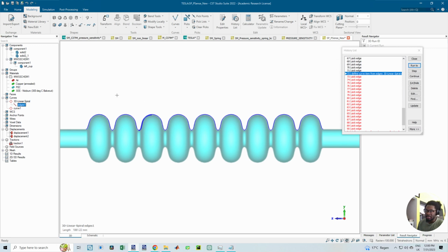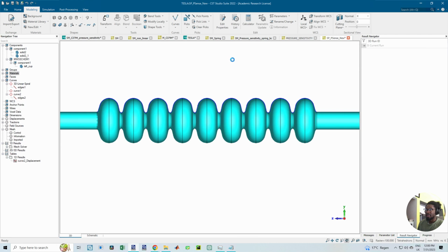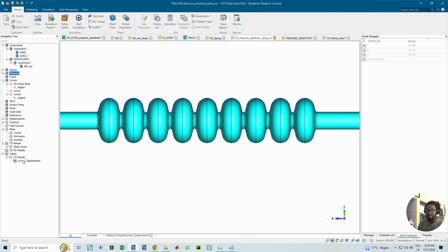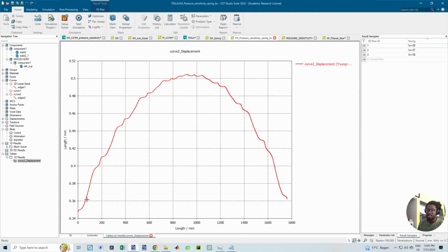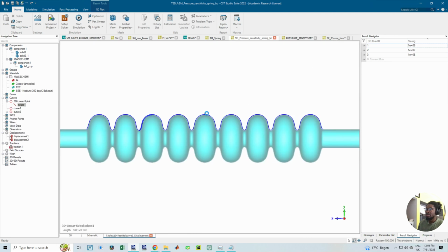Because I already had a result, and if I were to delete this, I would have deleted the results, I instead picked the curve again, this time correctly. So this is what I did, just so that I did not delete my results. Then I also defined the curve, and changed the material property for the sweep. First of all, I evaluated the displacement for 1e-6.